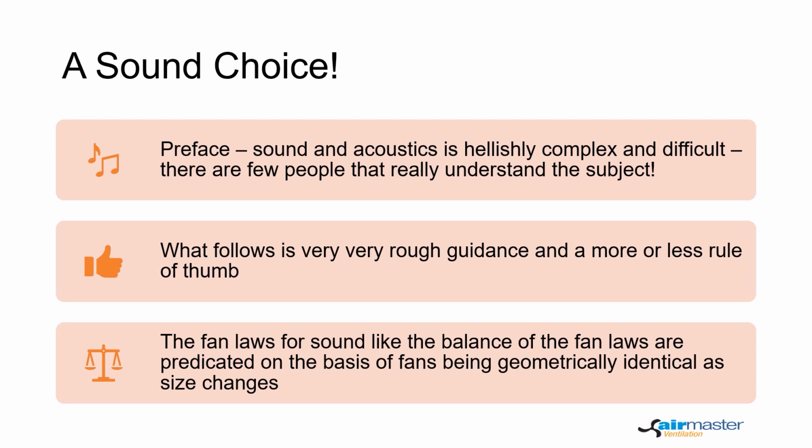And if there's anything else going on acoustically in that space, then it adds to the sound of the fan. They're also measuring not only the sound of the fan itself, but the reflection and refraction of the sound in the space. So suffice it to say, you can't easily measure sound except in very special circumstances and in very special ways.